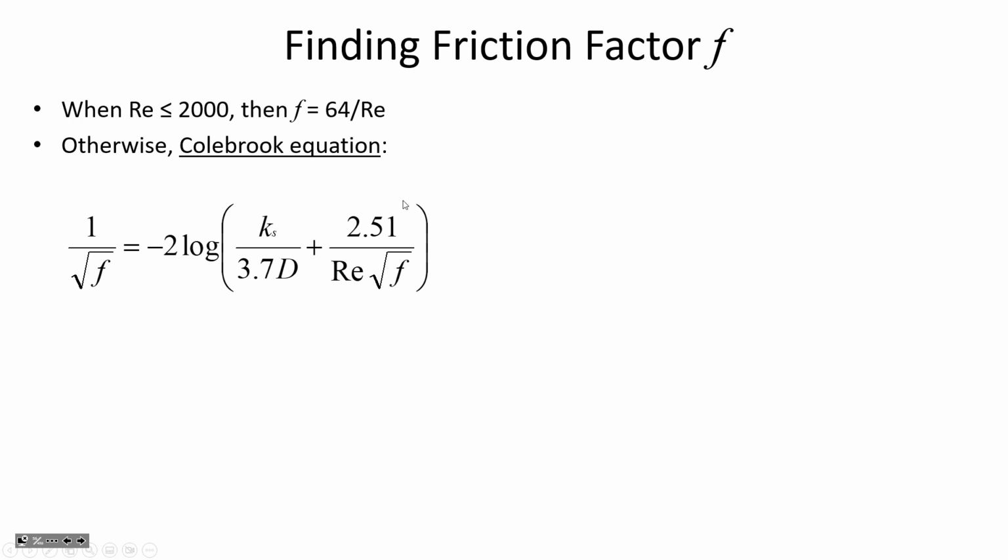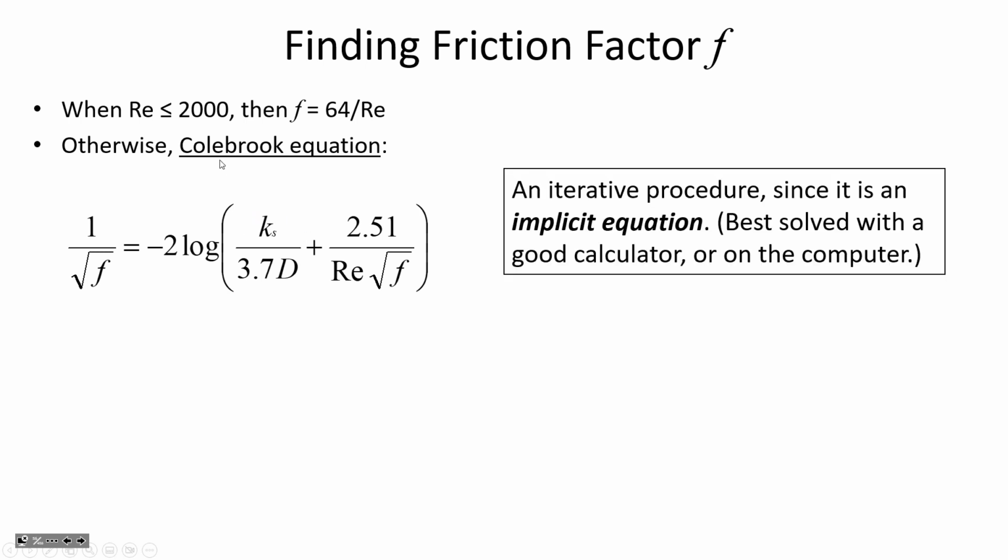It's tightly related to those two different zones on the Moody diagram. If you have a big Reynolds number and this term is in the denominator, as Reynolds number goes to 10 to the 7th, 10 to the 8th, 10 to the 9th, then since it's in the denominator, this second term is going to become inconsequential, and all that matters is the left term inside the parentheses there.